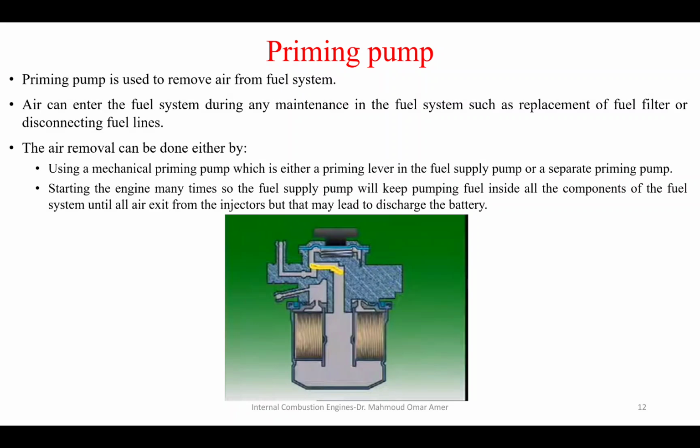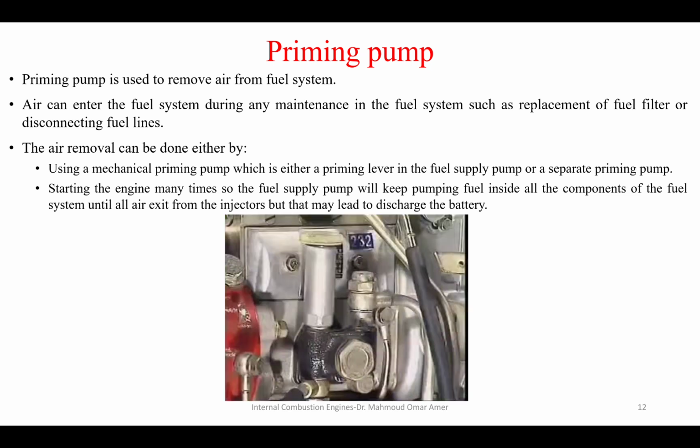Reed valves connect the priming pump housing to the filter. Pressing down on the actuating button reduces the volume in the pumping chamber, which forces fuel into the filter element. Releasing the button lets the spring lift the diaphragm, which increases the volume in the pumping chamber. Air pressure in the fuel tank then forces fuel into the pumping chamber.